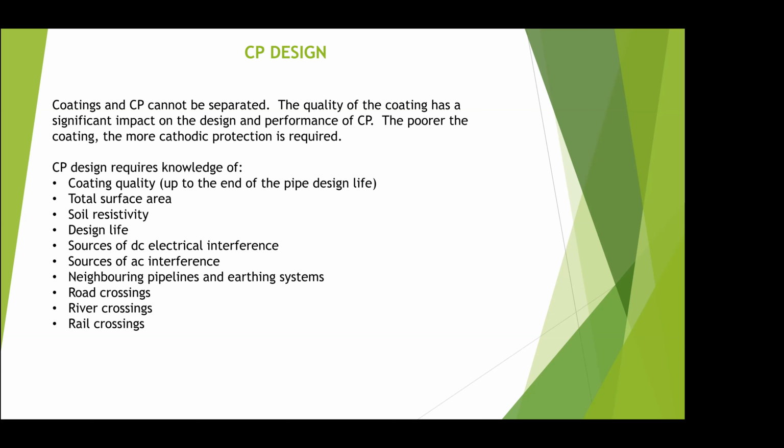And some people are smart enough to put inspectors in the coating shops and also do what they call holiday detection on the coating before it goes in the ditch. And then they just say, oh, repair it. Well, of course, that's a license to the contractor just to do the minimum of repairs with the minimum of tests. The coating repairs need to be as heavily specified as the original application of coating.